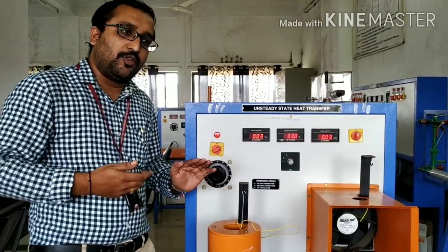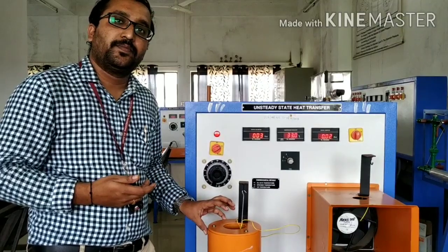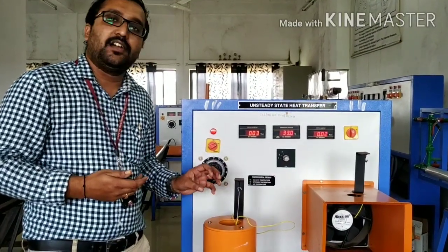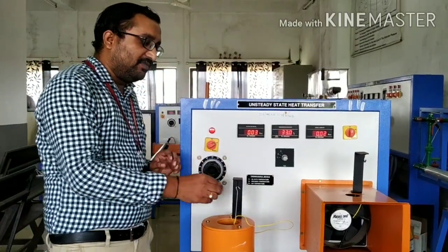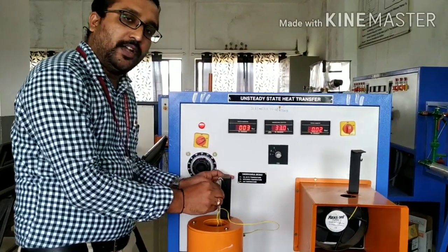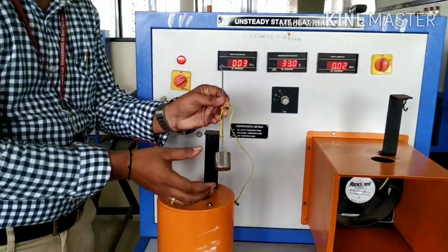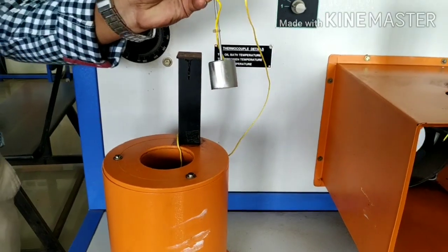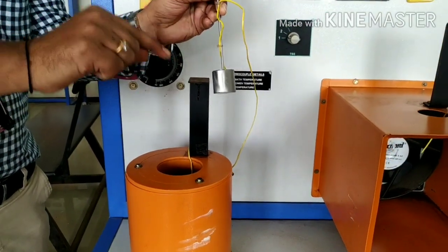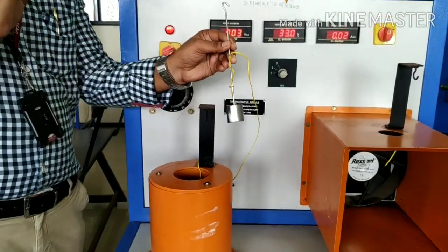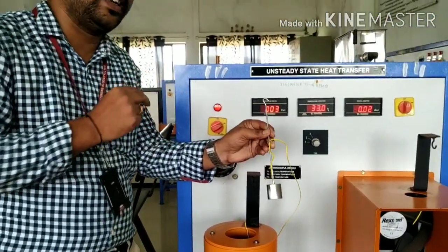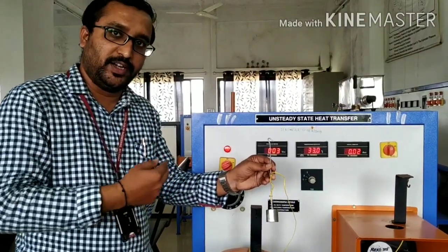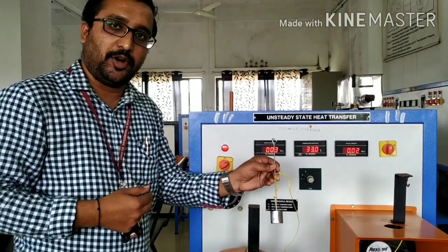So that concludes our experimentation about heating. That is the point where we stop the experiment for heating of the specimen. At the end of the experiment, T1 and T2 become equal, and the specimen is now a very hot specimen at higher temperature. During these readings, we understood that the specimen temperature has continuously increased with respect to time. That's why we consider it an unsteady heat transfer. Temperature is varying with respect to time, so it is an unsteady state condition for the body.